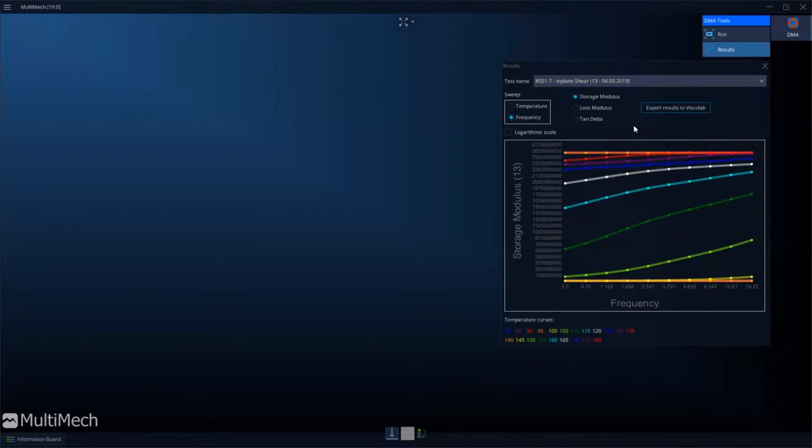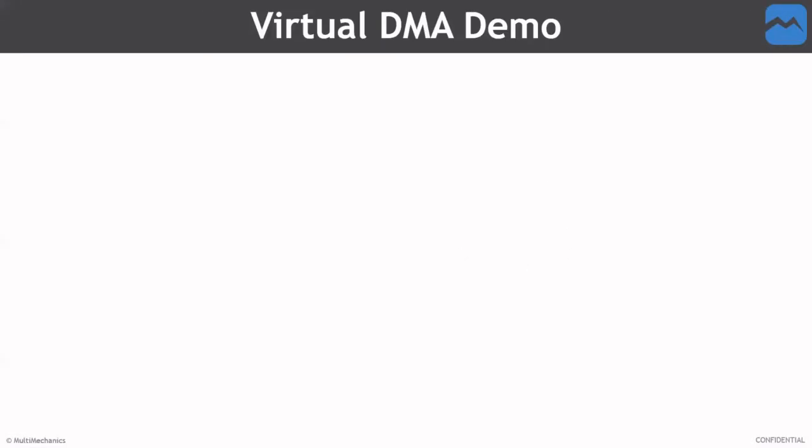So if you don't want to use the multiscaling approach for running a big layup and running a strain rate dependent simulation, you can now use an anisotropic viscoelastic material using this workflow to run quick simulations, and eventually run really large simulations too if you have to look at components that are really large. That concludes the virtual DMA demonstration.